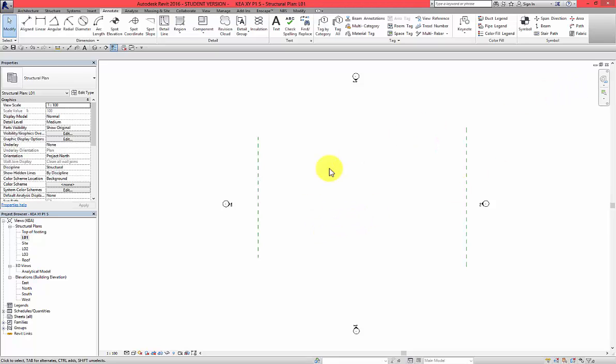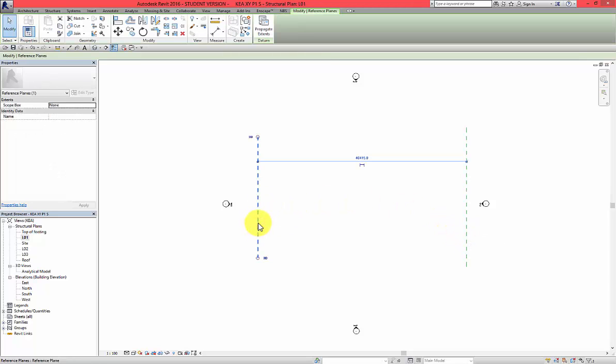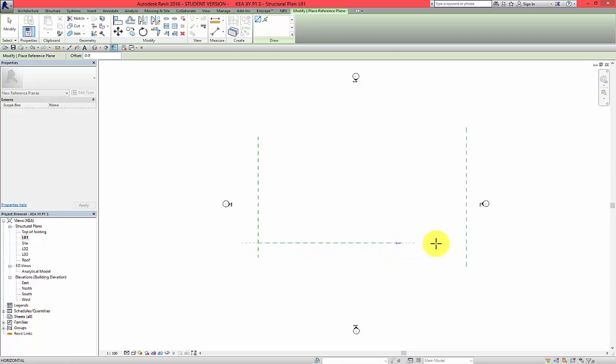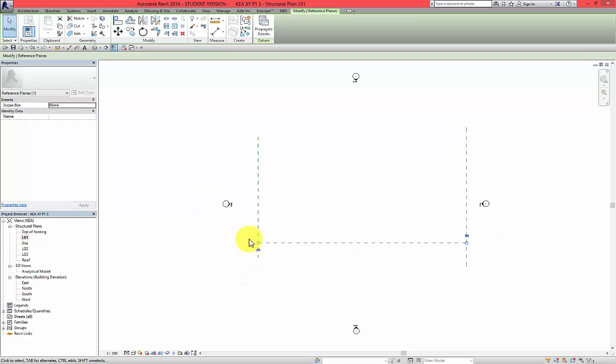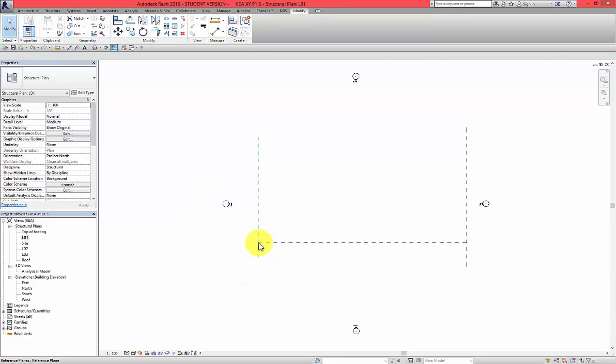The second step, I need a line that starts from here and goes to this line here. Left click, right click, create similar, and then start from this line, left click, go over there, snap to this line and left click, escape. Okay, we have a line, and then we need two more lines, the sides, we need two other sides of the triangle.